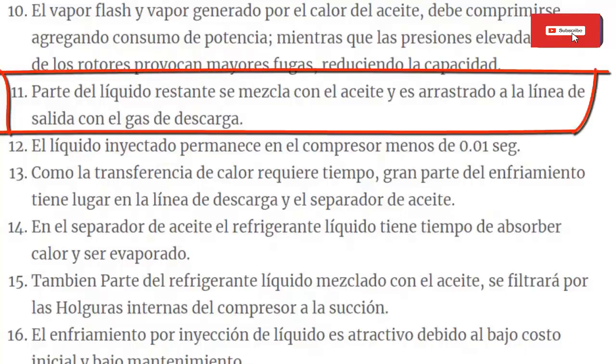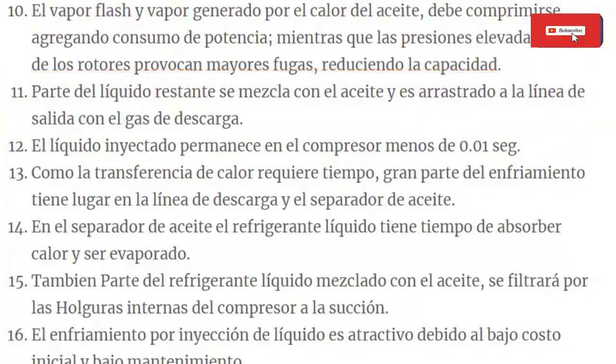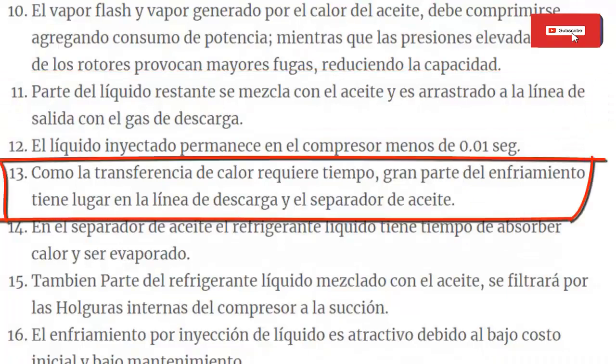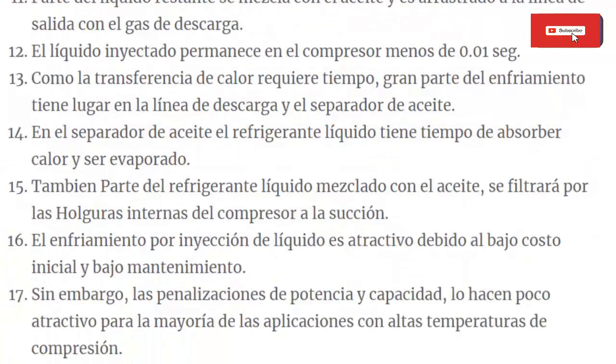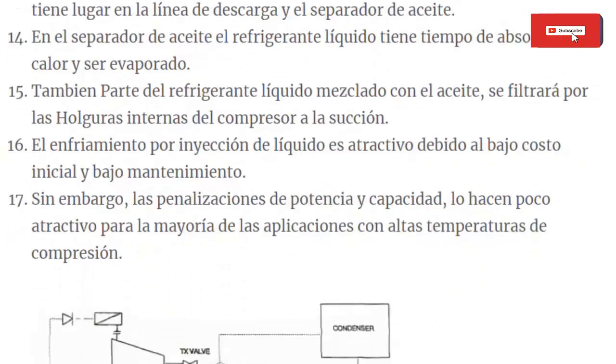11. Part of the remaining liquid mixes with the oil, and is entrained in the outlet line with the discharge gas. 12. The injected liquid remains in the compressor for less than 0.1 seconds. 13. Since heat transfer takes time, much of the cooling takes place in the discharge line and oil separator. 14. In the oil separator, the liquid refrigerant has time to absorb heat and be evaporated.